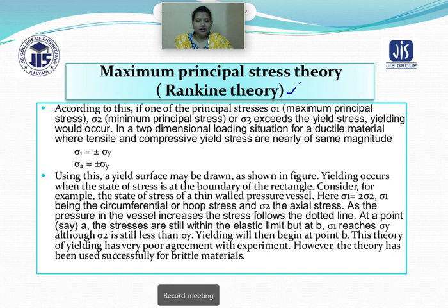That is, if you consider sigma 1 as the maximum principal stress, then it will be twice the minimum principal stress for your pressure vessels. This maximum principal stress is also known as circumferential stress, or hoop stress. As well as if you talk about sigma 2, this is none other than the minimum principal stress, also known as the axial stress.